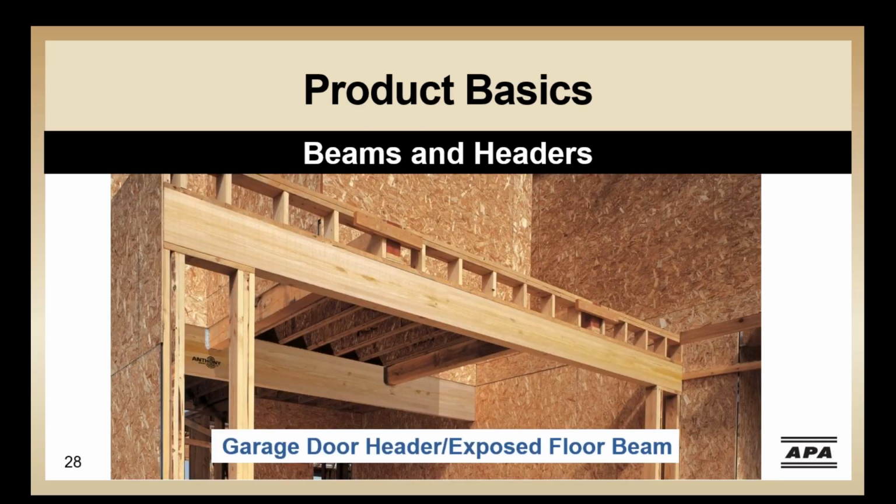Here you can see a typical header for the garage door and an exposed floor beam in the center of the garage. As you see in this situation, the appearance isn't paramount to the end use of the beam. Therefore, a framing classification or industrial classification for this glulam beam can be used. As mentioned earlier, beam headers are available in lengths that will allow extensions on each end of the garage or window opening to help builders meet code, where there's a little bracing on either side of the opening to create a portal frame.